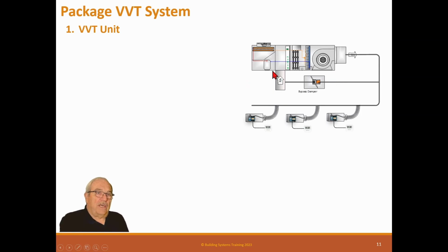So originally when these came out, these didn't work very well. And the reason was there's several units. I've retrofitted many of these systems. Originally they didn't think about this damper like this. They just came up here and put a damper right here in the duct and blew down into the return air plenum. And said, we can make it VAV, we don't need this connection. Well, what happened was, since they weren't TAB people, they didn't figure this out, is that when you open air like that above a plenum, you think, well, it's wide open. Well, it has microclimates above there, and it will pressure that zone right where it comes out.